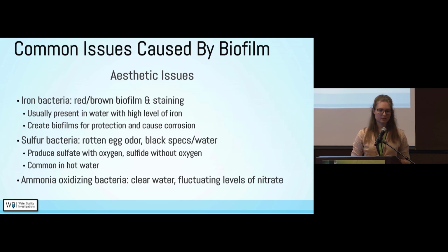We see sulfur bacteria. They often cause rotten egg odors, black specks, or black water. They produce sulfate in an oxygenated environment, sulfide without oxygen. We see them a lot in water heaters and hot water systems. Ammonia oxidizing bacteria are often present in water that looks clear. We all know that clear water doesn't necessarily mean good water, but that does still mean that there's bacteria in the water. And so if we have nitrate or ammonia for those bacteria to work with, they can convert those.